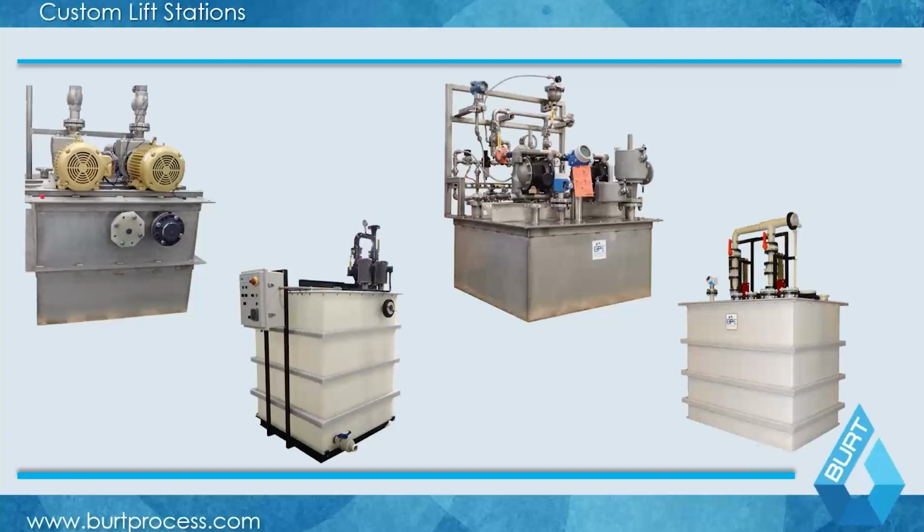You may have different chemicals that could be hazardous, i.e., explosive chemicals, such as solvents that aren't going to go to the pH system. They go to more of a solvent collection, and you have explosion-proof design lift stations. If your flow rates are really high, you're going to be outside of a 260-gallon tank. So if you have a 250 GPM or 300 GPM flow, you have a residency time of a lift station that could be 1,000 or 1,500 gallons, really scaling up from there. Some of the lift stations that I've worked on have been 2,000 or 3,000 gallons, for example, or up to 15,000 gallons if you're supporting a large enough flow coming into it.